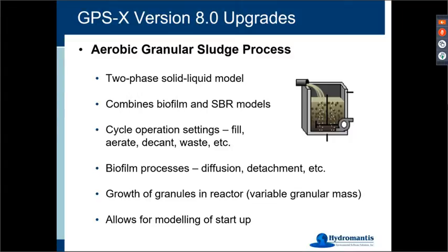Okay, so let's talk about the one that probably we had the most requests for, which is the aerobic granular sludge process. So this is a 2-phase solid liquid model that combines the best of what we do with our biofilm models with the way that we operate our SBR models. So this allows you to model it in the way, like the Nereda system, where you will fill and aerate and then have anoxic times, and then you let it settle, and then you decant. So it needs cyclical operation settings.